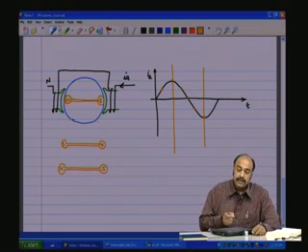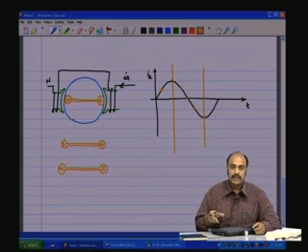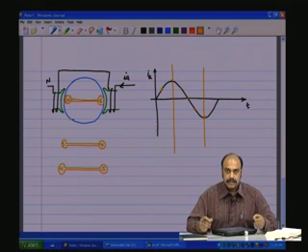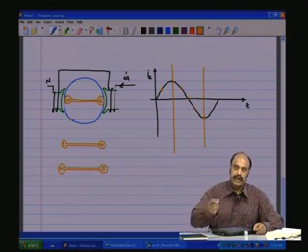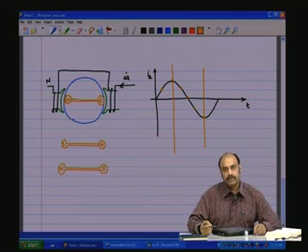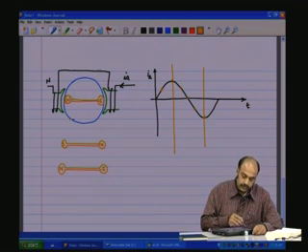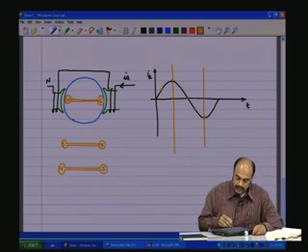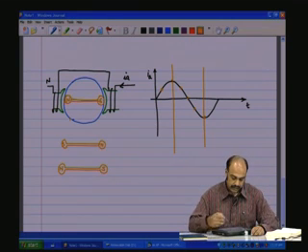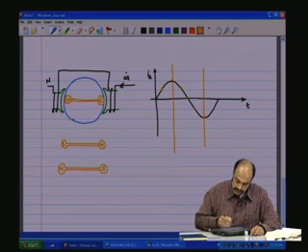So inside, if we take the imaginary dumbbell on the rotor rotating, it means that the flux MMF inside has rotated 180 degrees for a half cycle traversal of IA, and it would have rotated a full 360 degrees for a complete full cycle traversal or 2 half cycle traversal of A. That is for a 2 pole system.